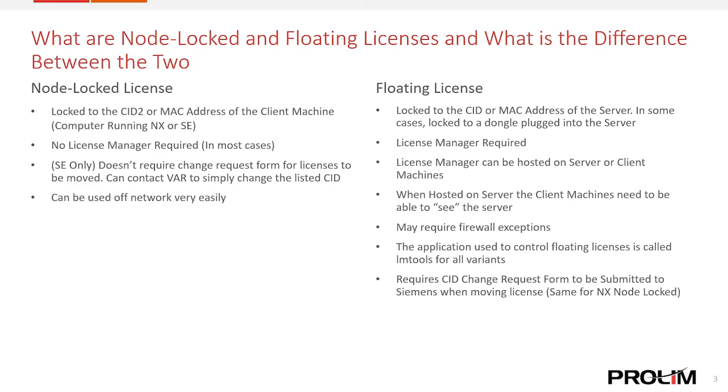I'll show an example of this, but all you have to do is launch a command prompt window. You just type CMD into the Windows search bar. And then in the window that pops up, you can just type in ping, P-I-N-G, space, and then whatever the host name of the machine is that is hosting license manager, whether that be your server, a client machine, or John's machine, whatever the name is, that host name.